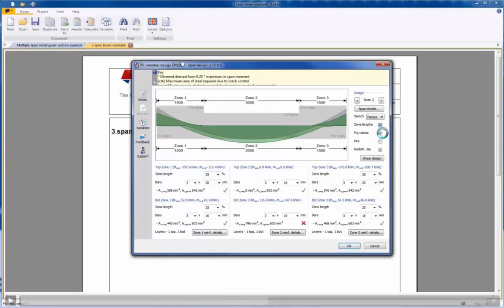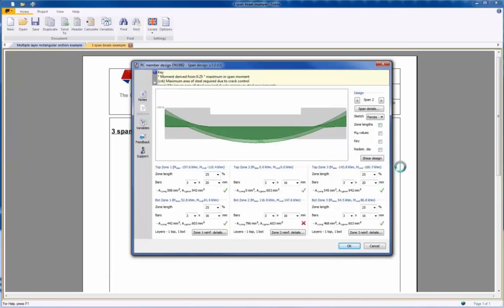So the first thing to look at here is we split it into 2 areas. We've got the reinforcement at the bottom here, and we have the sketch showing what's going on at the top. I'm just going to turn off some of the settings on the sketch. We'll look at that first. If I trim that down to the basics, what we've got here is the grey area is the capacity, and the green is the actual design forces. So as long as the grey encompasses all the green, the beam is passing.